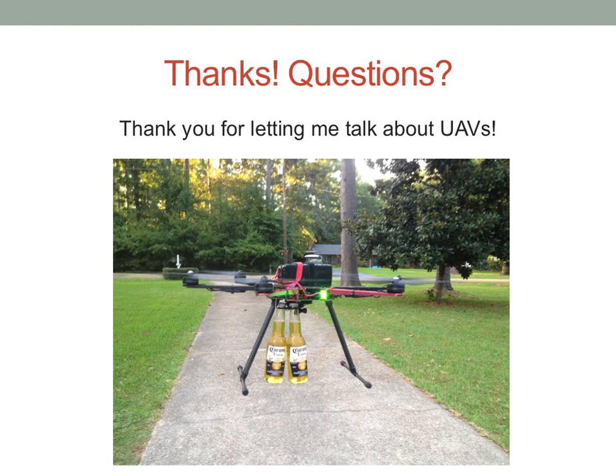So the whole thing with this is weight, right? The less weight that you have on there, the longer flight time that you could have. Each one of those bigger motors produces 600 grams of thrust at 50% power at hover, so I have 600 grams times 6. That's the maximum amount of weight that I can carry with that motor configuration. If I had the least amount of weight, the smallest camera, the smallest battery that would produce the most amount of energy, that's what's going to influence my flight time, to be able to fly for 2 hours, 3 hours, 4 hours, and just have it going.